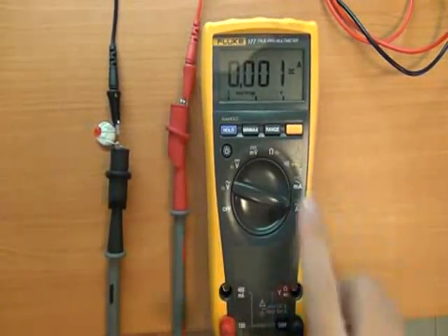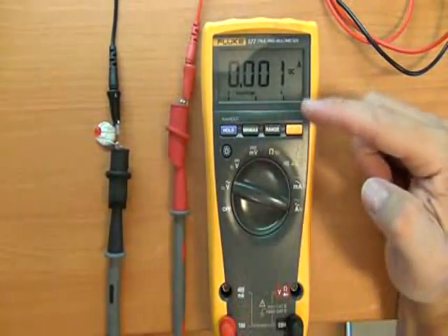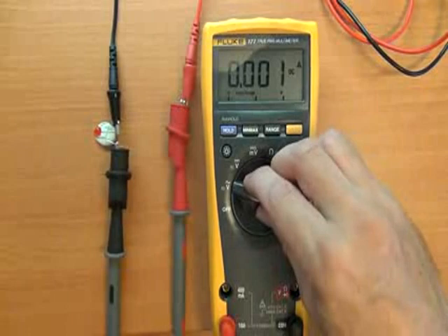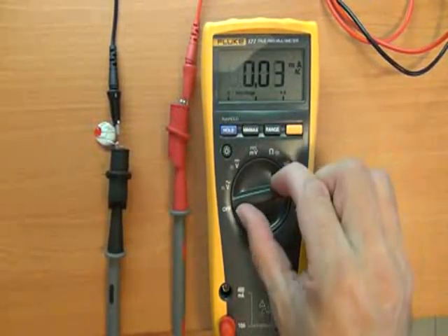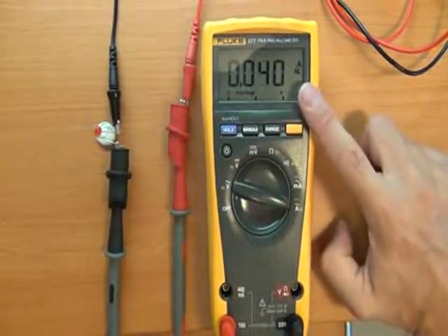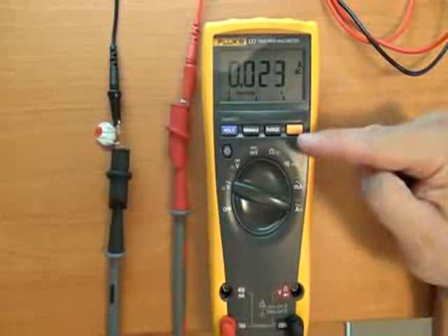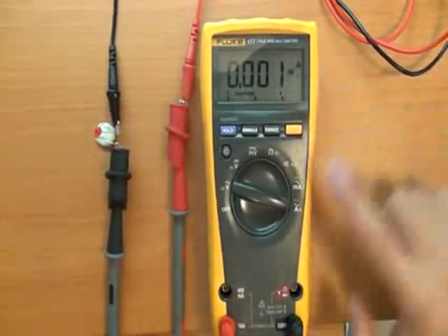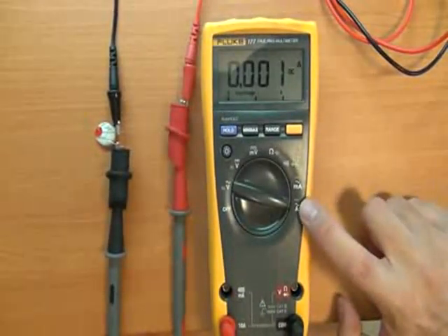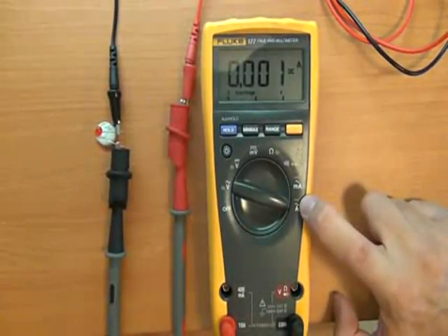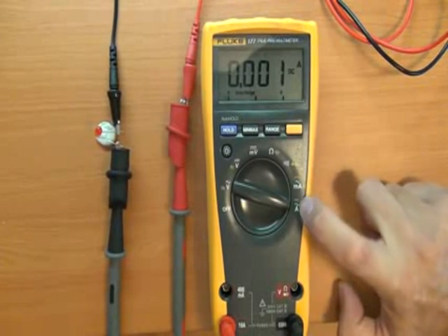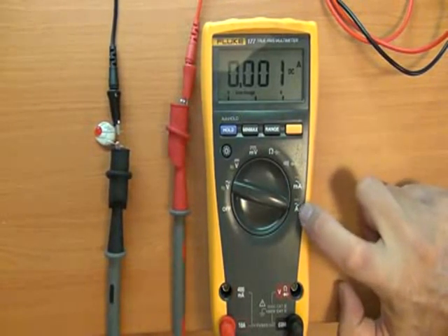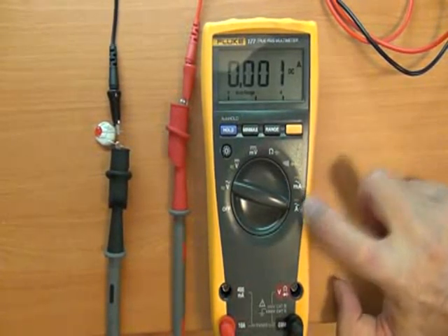We've got our multimeter on ready, and remember, on the 177, if you happen to change any of the settings, it's going to default back to AC. So remember to use the secondary function key here to go to DC, which is noted, as you can see here on the multimeter, in orange, the DC symbol above the AC symbol, which is the default.